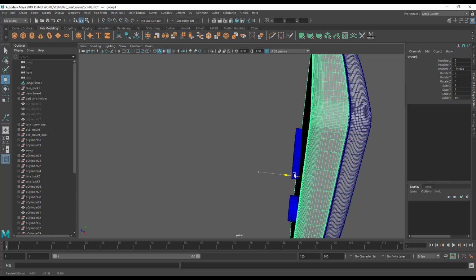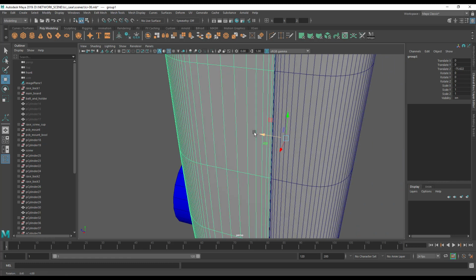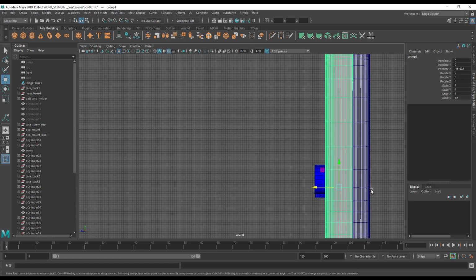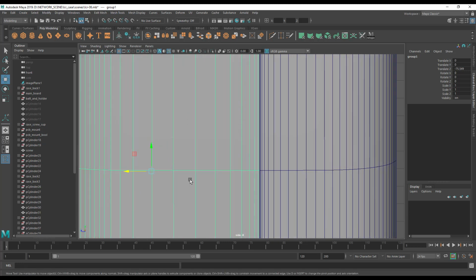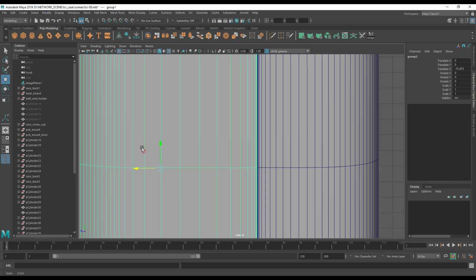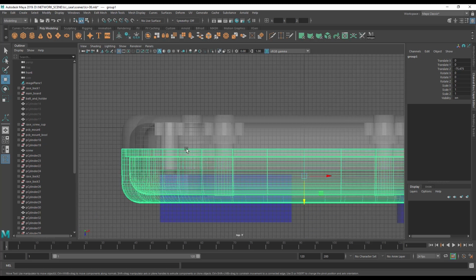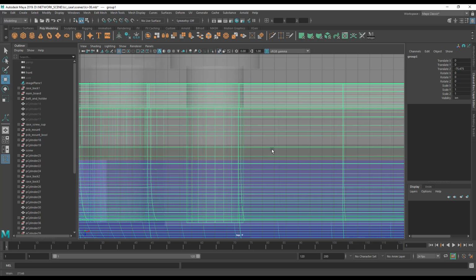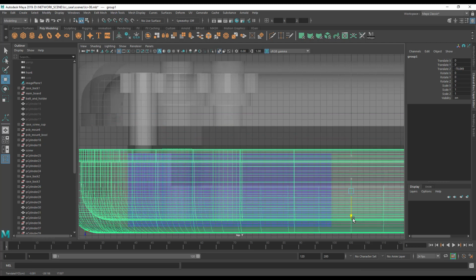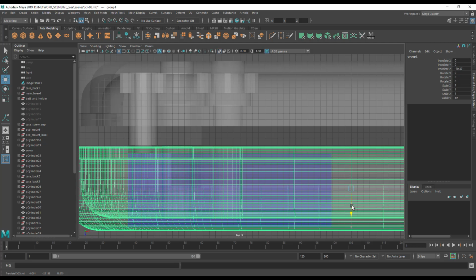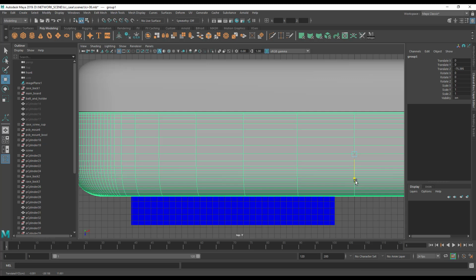Let's get the case shut up. So we want a fairly tight seal on it. So somewhere like there. Actually, probably be easier to see in this view. There we go. And if we look at the top of this under X-ray conditions, you should see that our shafts match up. So is that actually matching up? This has honestly become quite difficult to see. Let me just turn off X-ray a minute, make sure that's lined up.